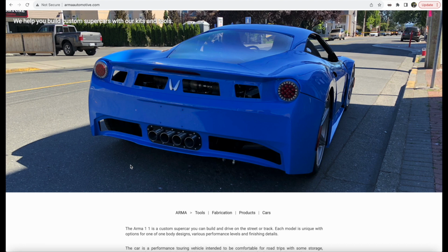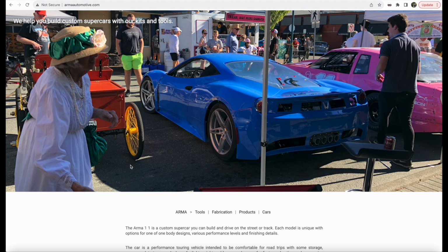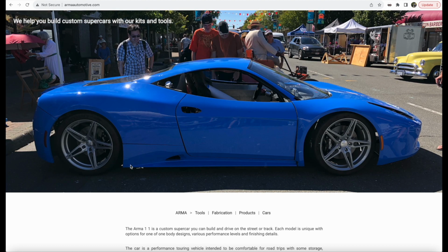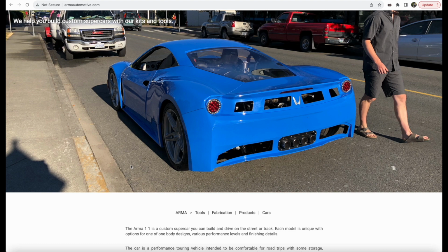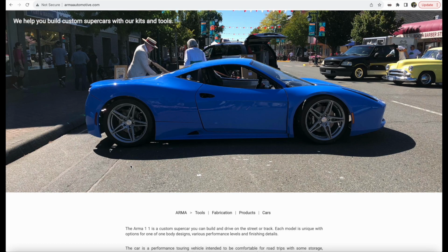This is a demonstration of our new pie cut tube routing feature, which we're going to use for exhaust headers, specifically equal length headers, and also other piping and conduits that need to be routed in tight spaces using bend radius that are smaller than a manual or CNC tube bender.